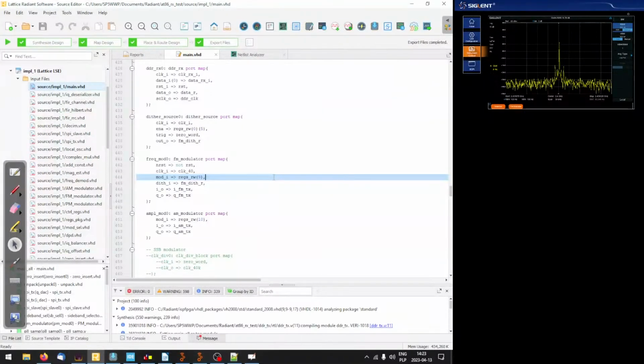It's a tone coded squelch for analog FM systems. So normally, when you use your radio with analog FM, you set the squelch level so that you don't get too much noise in the speaker, because if there is no transmission, there is just noise, and you want to avoid that.